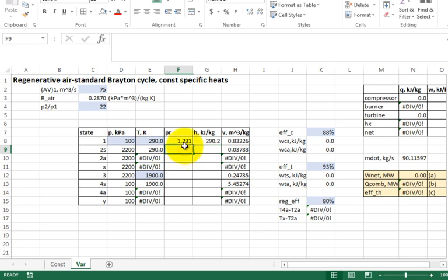All right. Now you think, we're going to go to state 2s. Basically, you're using the equation that PR subscript 2, the PR at the new pressure, is equal to PR1 times that ratio of pressures. It's equal to this first PR state 1 times the pressure ratio. There it is. Now, for this state, I like to label stuff right here: knowing the temperature, I was able to get PR and H.